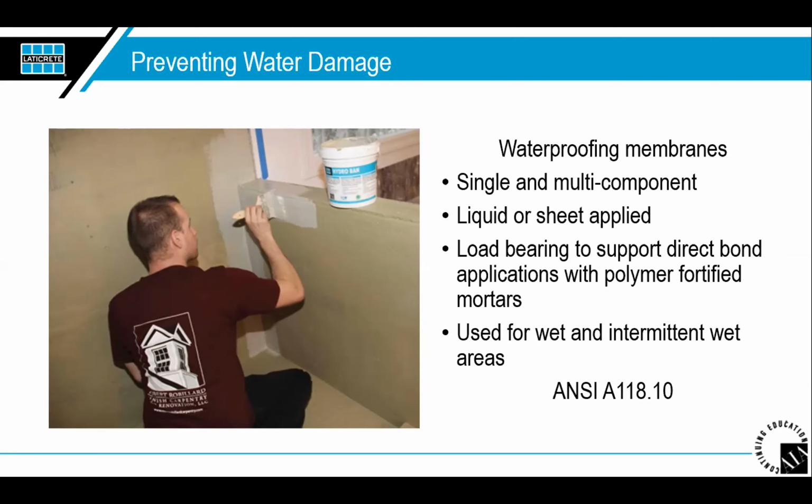it may require, like I said, a primary roll roofing membrane, which can be a peel and stick. They can be different types of adhesives to put on, but definitely get with your project engineer on that one to say, okay, how are we treating this and what are we doing here? Sometimes just using waterproofing in those scenarios is just not enough.